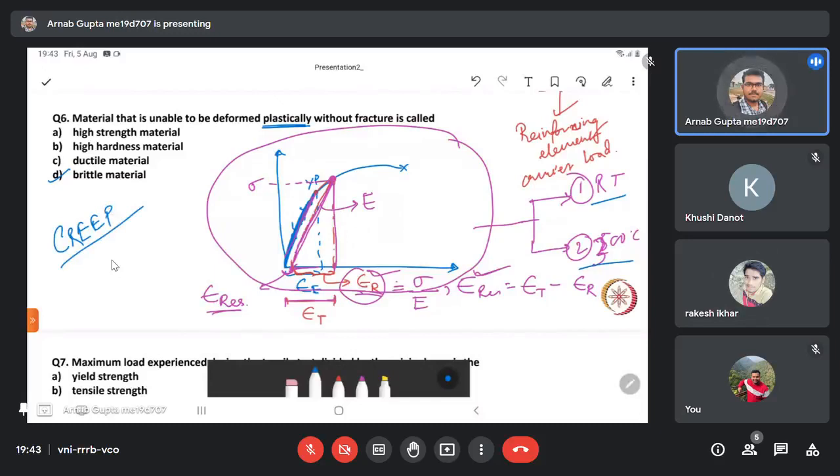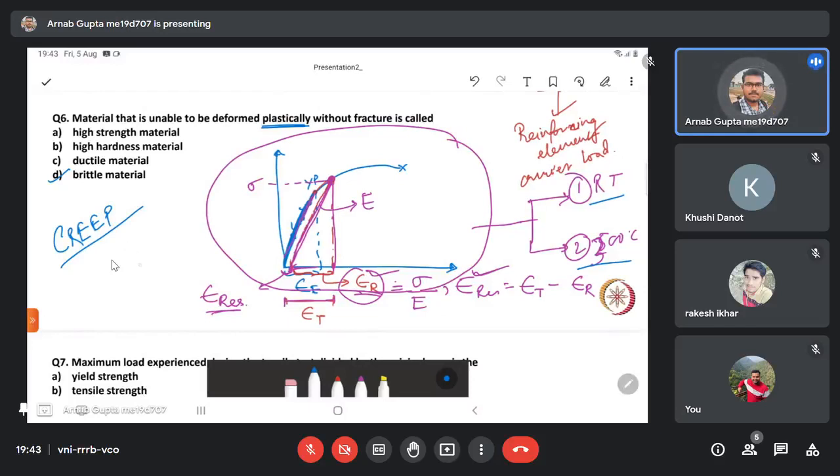So see, basically the decrease in Young's modulus is not creep. Rather, we would say that if we are subjecting a material to a constant load, say the load is not changing, but at an elevated temperature, we see that the material is getting strained. Okay. So see, from this particular graph, at a given strain, we will say that the stress value is this much.